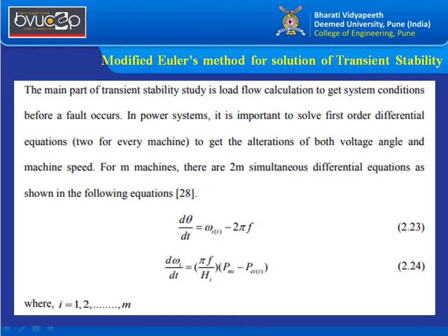So whenever there is a fault or there are certain changes in the power on a real time basis, we can do the calculation using optimal power flow analysis, and considering those values we can predict whether the system will go into a fault or not, prior to the system going into the fault. So that can be considered in the planning stage, considering the historical data we have.